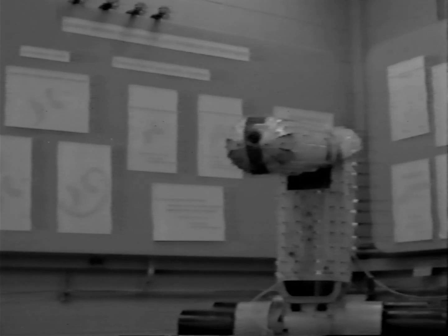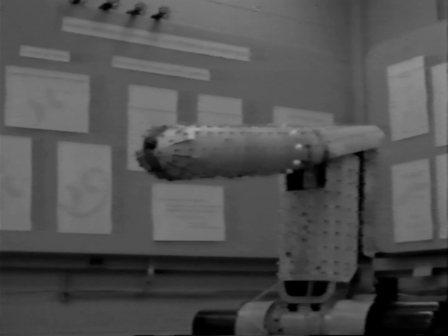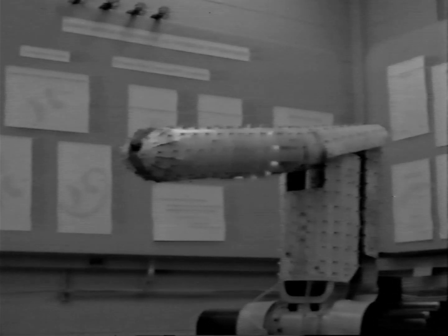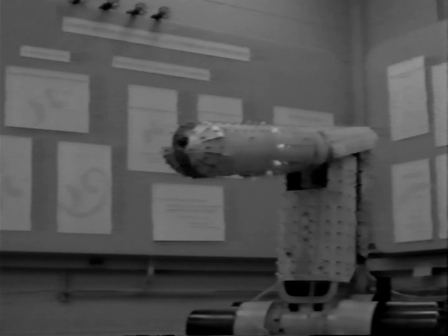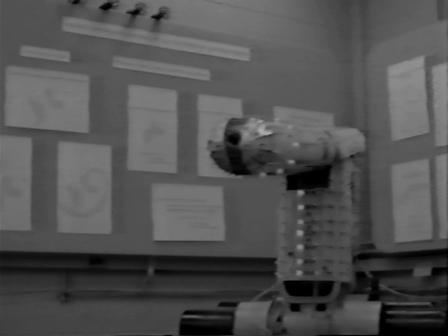The sensor operates at a distance of up to 5 inches and uses amplitude-modulated infrared light for the detection, which increases its immunity to ambient light. To give the viewer some idea of the time multiplexing sequence, the scan shown here is slowed down approximately 15 times.